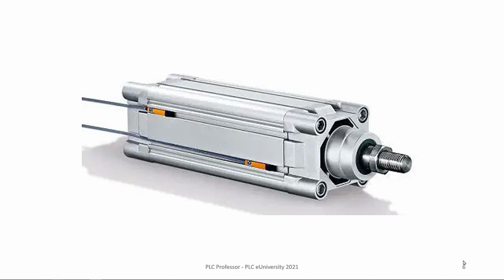That's a Hall effect. And you can see they slide into slots, and then there's a little set screw. This graphics resolution is not that great, but the little dark circle in the orange, or maybe it's in the black, is a set screw. You loosen it, you put the piston in the position you want to sense, and then you slide the sensor until it sees the piston.